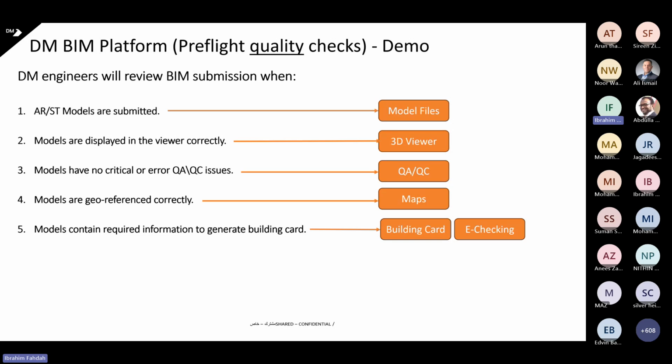So you look at those failed rules and make sure any failed one is just a false positive, which means yes, it's failed, but when the model comes to the engineer, he will know that the system could not recognize the full context, so that it should be green. But because nothing is perfect when it comes to machines and computers, you can ignore that. But if there are genuine failures, you need to go back to the BIM model and rectify the issue so the rules pass.